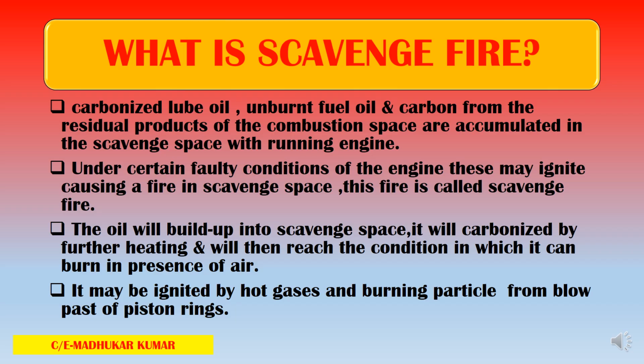In this under-piston space, or the scavenge space, the accumulation of unburned fuel or carbon is going to happen, and the blow past is basically the trigger, or you can say the source of heat. So this is going to cause the fire. The oil will build up in the scavenge space when the engine is running. It may carbonize, and further heat will then reach the condition where the burning of these fuels can happen.